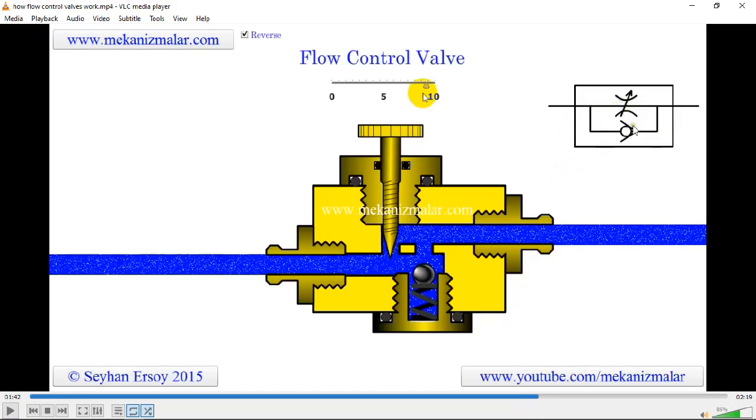It has a throttle and it has a check valve. If you apply pressure from this side going this side, and look at the throttle, the arrow points towards your right direction. So it regulates the flow of air that is going forward. Because whenever the pressure tries to take this route, it is blocked in a check valve. Check valve only allows pressure to flow in one direction.